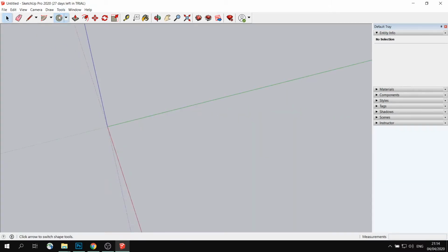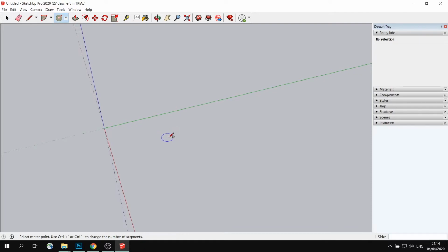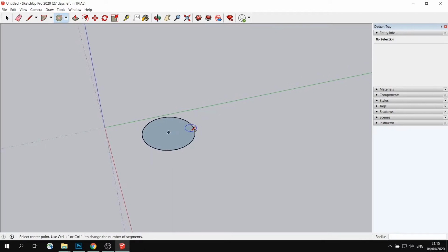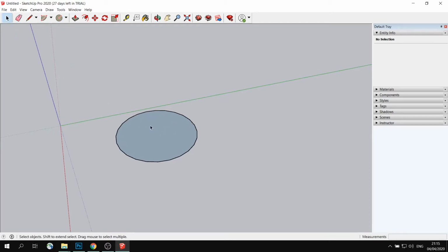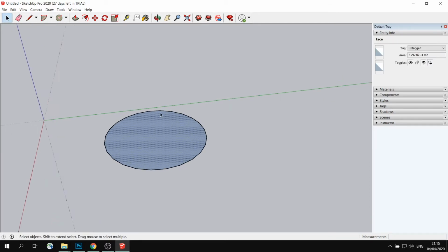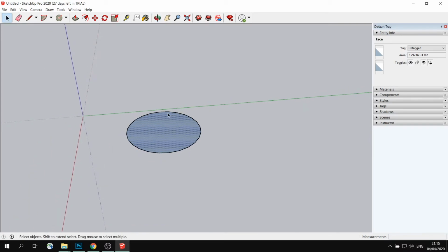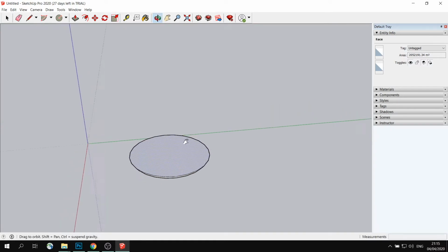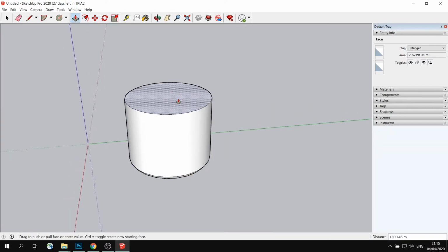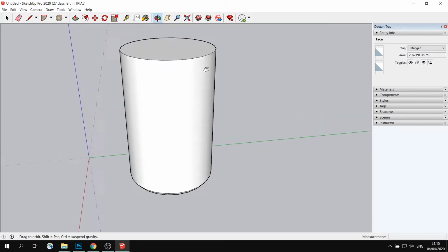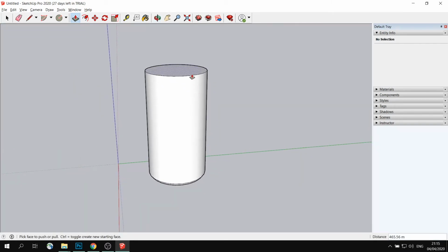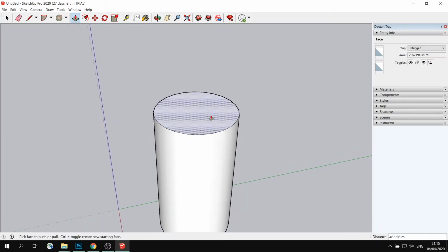Okay, so now let's recreate a wine bottle just for the practice sake. It is important that whenever you're doing 3D modeling that you just practice different shapes. So I would do, for example, a vase, a bottle, a can, things like that. So here we'll start from the bottom. I will extrude that part upwards, then I will scale it again holding Control so it scales into all directions like that. So this will be my bottom part. Then I will extrude this part like that, maybe a little bit more. That looks kind of like a wine bottle, I guess.